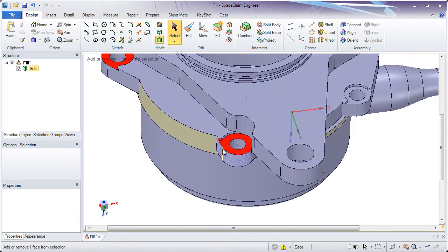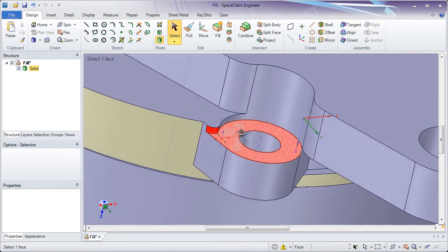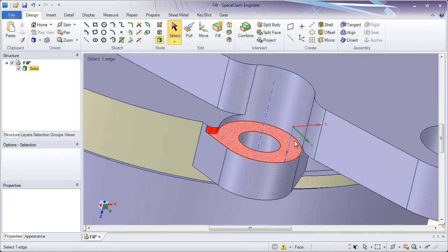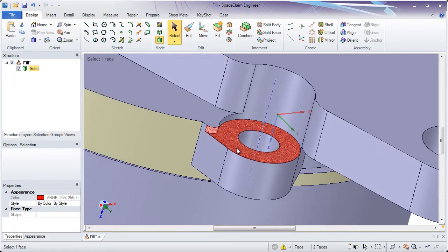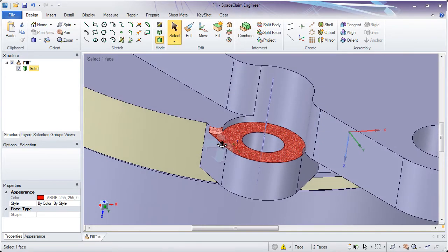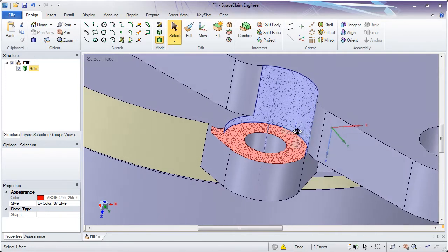Now the last example I want to show you are these red faces here. Let's say we wanted to remove this little small inlet here. You'll notice we box select them, we have the red faces selected, but now how is this going to extend to remove them? This face, I guess, will extend here and here to form a sharp, but this face will never extend up to this one. How is it supposed to know whether to extend this and to clip these faces here?